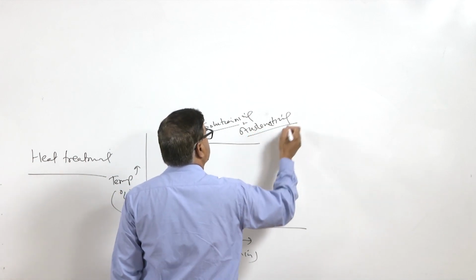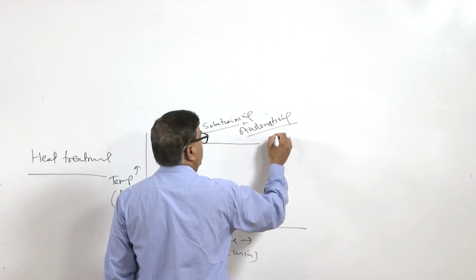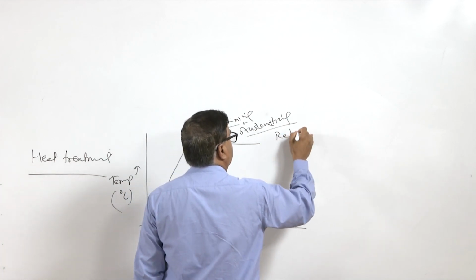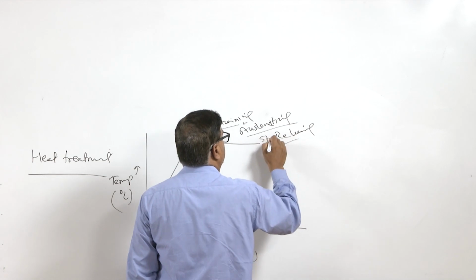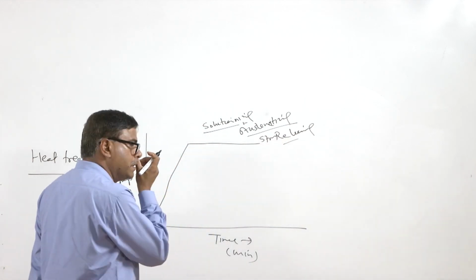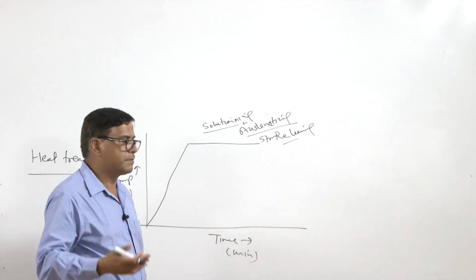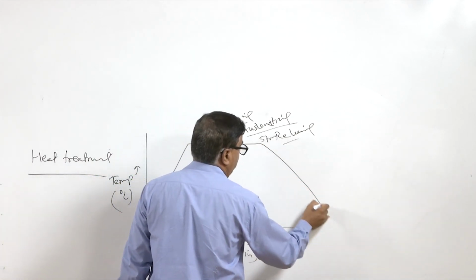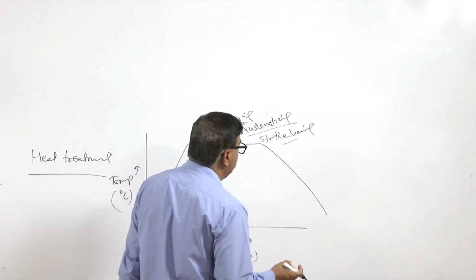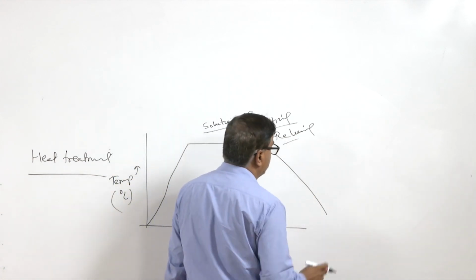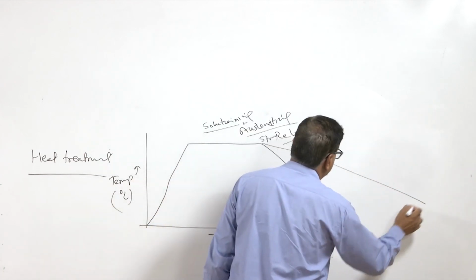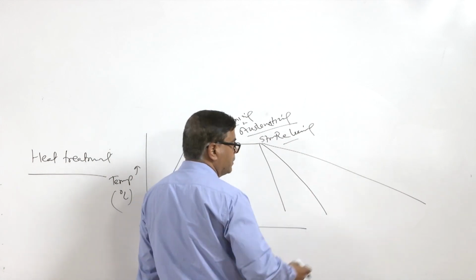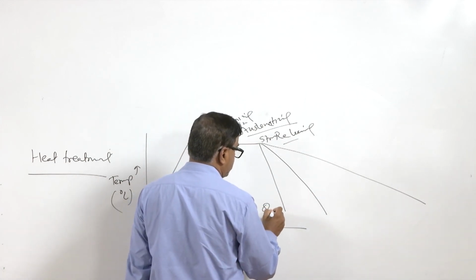And then it may also be done for stress relieving, at the stress relieving temperature. It is expected that there won't be any phase transformation during the stress relieving, and thereafter, as per the purpose, different cooling rates are applied. It may be cooled very slowly, or at a faster rate, or at a very high rate. So, depending upon the purpose, the cooling rate is used